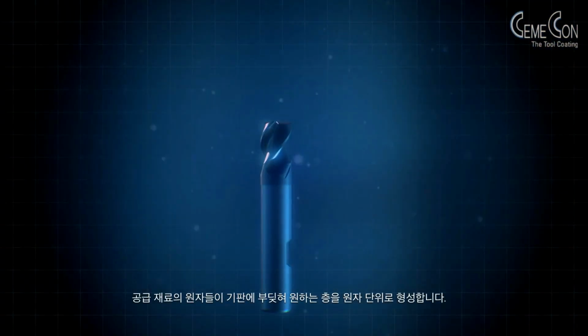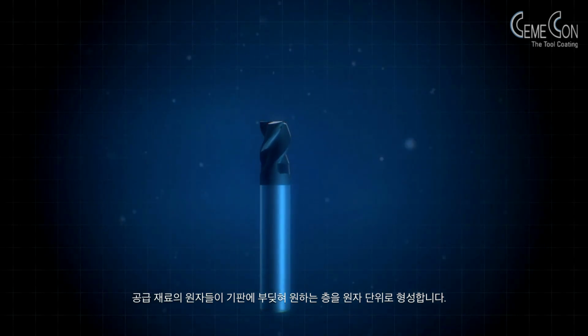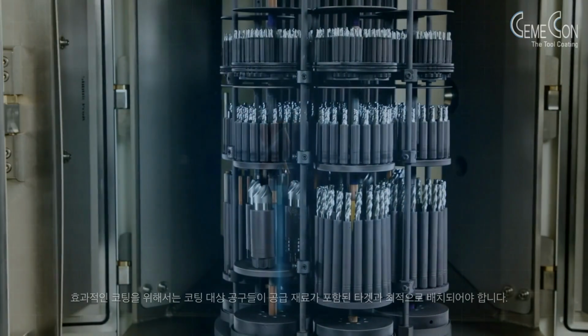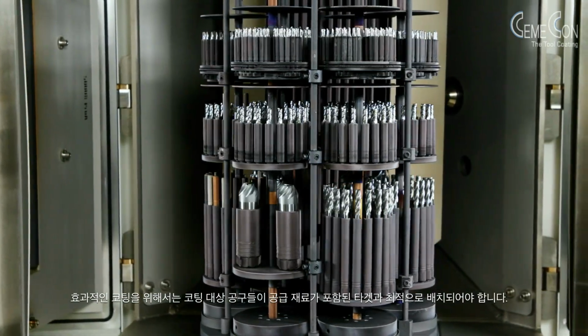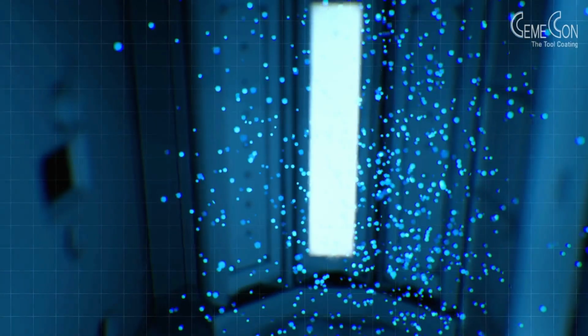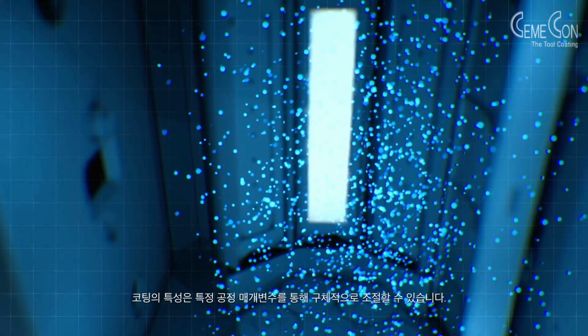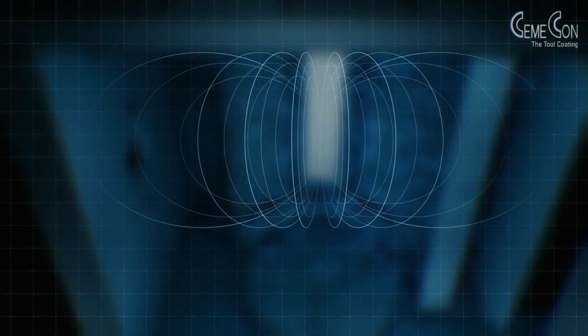The atoms of the donor material hit the substrate and form the desired layer atom by atom. For this to happen effectively, the tools to be coated have to be optimally aligned to the targets with the donor material. The properties of the coating can be specifically influenced by means of certain process parameters.